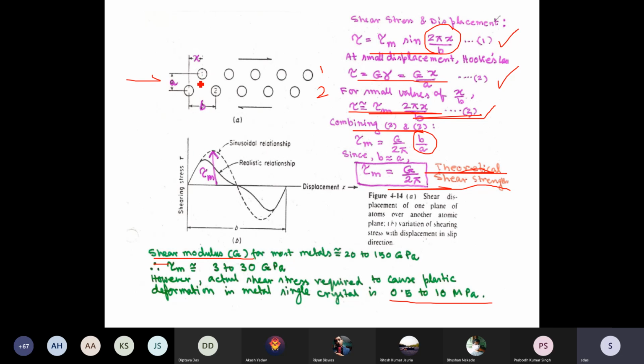During this calculation, what happened? There was a bond between the atoms. When I am gliding one atom over another, I am breaking this bond. I'm breaking this bond. I'm breaking this bond. And to move one plane of atoms over another plane, the bonds between the atoms on the top layer and the atoms just sitting below in the bottom layer, each bond has to be ruptured at the same time, so that the first layer of atoms will glide over the second layer of atoms. Any question?